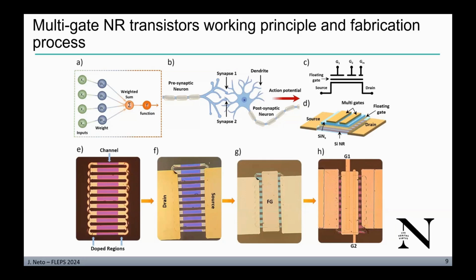Of course, the device size would vary, or the width of the gate can vary. The gate width would define the weight, basically, in this case. So depending on your prior training, what you want to have, you can embed this into the device itself. This is the overall structure: you have the silicon, then the silicon nanoribbon, then the floating gate, then nitride, and then multiple gates.